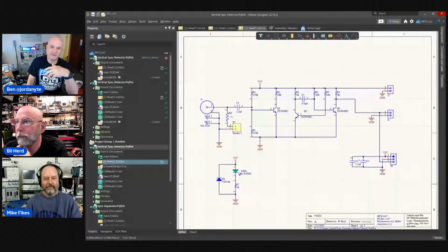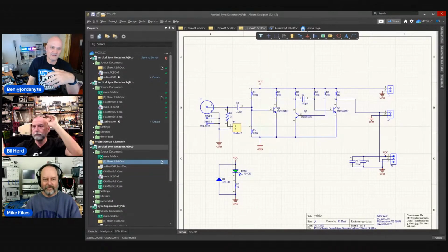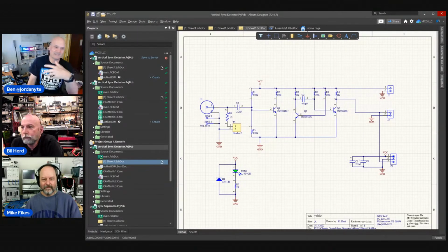It's ngSpice underneath, so it's all the same speed. It's all the same performance, same types of simulation ought to be available. Sometimes, like in Autodesk, they haven't finished the Spice user interface in Fusion like it is in Eagle. So there's limits to what you can do.